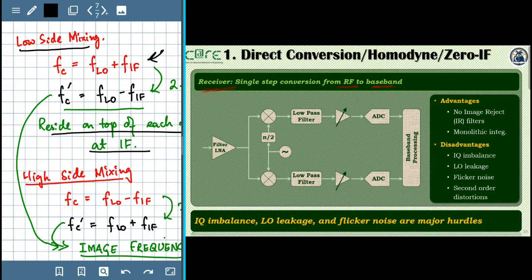In this case, you see that the received signal is being filtered and fed to a low noise amplifier, LNA, and after that there is the process that you have seen in the beginning of this tutorial, the process of down conversion from the RF to the baseband. It involves an IQ mixer again and a low pass filter.